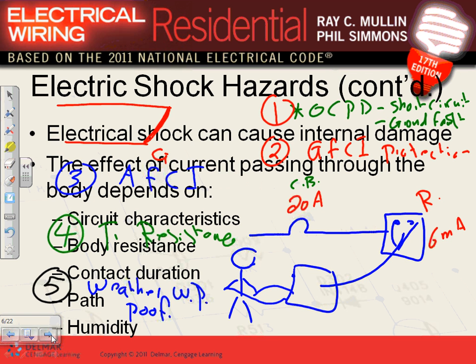Now you can have all of them or you can have some of them. In residential, guys, here's the must. Let me highlight the must, the must have in red. This is the must. For every circuit, you must have overcurrent protection device. You can't just go without it. GFCI, we know where the GFCI is located, almost in every wet or damp location, and we listed the location.